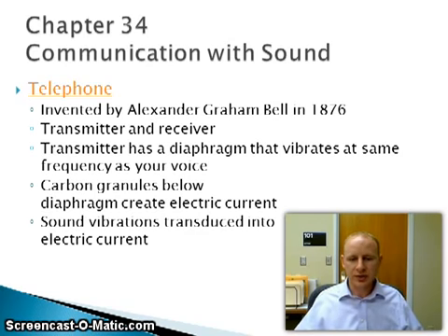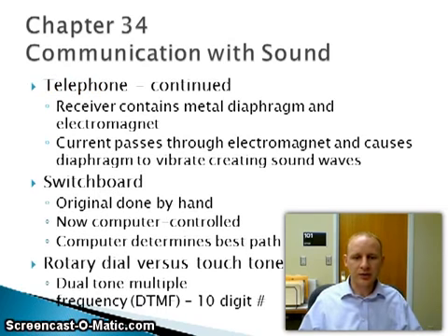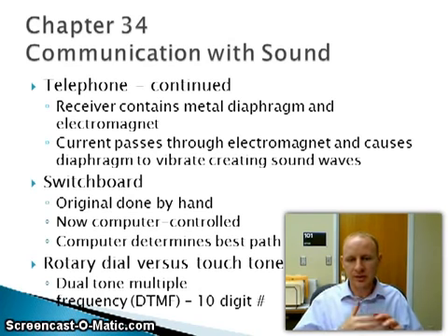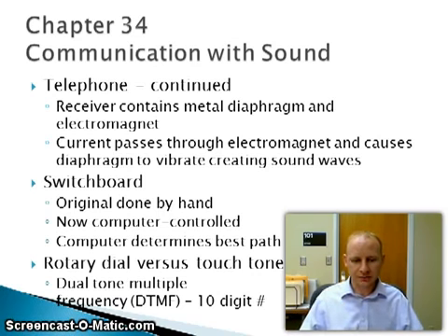So the sound vibration is transduced into electric current from the one end, which then goes to the other end, which has a diaphragm and electromagnet. As the current passes through the electromagnet, it causes the diaphragm to vibrate, creating sounds. So really it's very similar to the telegraph, but instead of transferring dots and dashes, we're actually transferring audio sound. So our voice creates vibrations on the microphone end, which then send an electric current through the lines to the other end, where those vibrations affect a speaker, which then creates the sound.